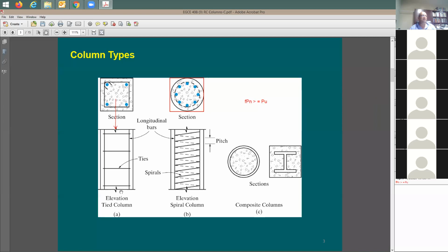If you don't have these ties, and all of a sudden now you start to apply the vertical load, what's going to happen to this vertical rebar? Vertical rebars want to do this, right? Correct? Yes. Wants to come out. And actually, the entire section of concrete, if you start to apply vertical forces, you're going to see here some lateral forces, right? Actually, it wants to open up. Those are going to actually act as a support for mid-span or whatever, for the vertical rebars.